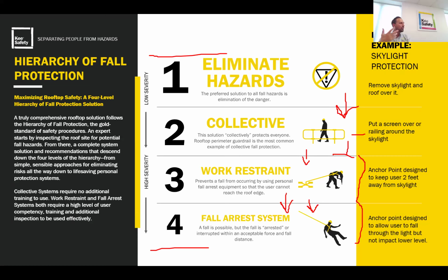And when a fall occurs, I need to, one, have enough fall distance for that to safely happen. Two, I need to have a rescue plan in place to get that person down in less than 15 minutes so they don't have suspension trauma set in from hanging on the side of the building. And three, I need to know that they fell, right? I need a warning system, a buddy system. I need a robust monitoring system to make sure that I know when somebody fell off of my building who's probably unconscious because they probably slammed into the side of the building.